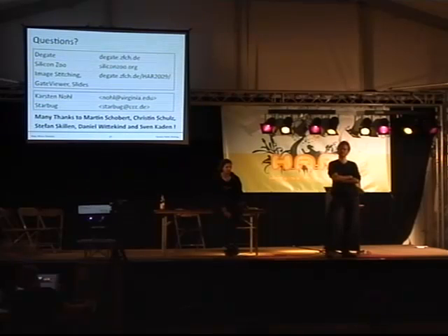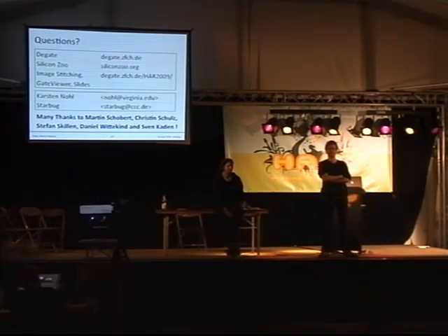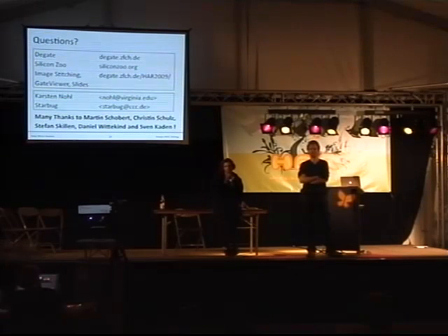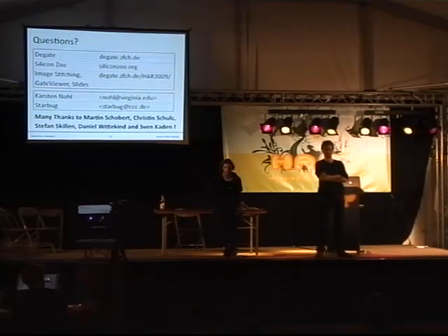Do intentional backdoors exist in smart cards? I don't think so, but there's enough unintentional ones. As in, trigger this debug pin and I will tell you my password, this type of backdoor, right? But I don't know if you would call it a backdoor, just a design flaw. So we found some parts that looked like fuses that had been cut afterwards, so maybe that's something you can connect, a debugging port or something, to bypass the password. That's possible. Right. Check out FlyLogic's blog, Flylogic. They have nice documentation on hacking smart cards, and most of which should apply to TPMs as well.